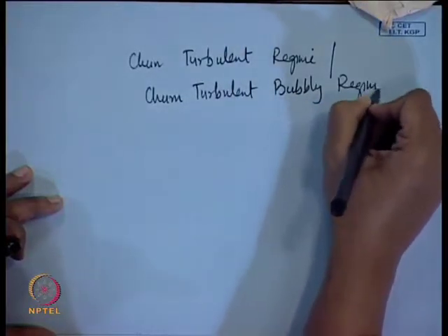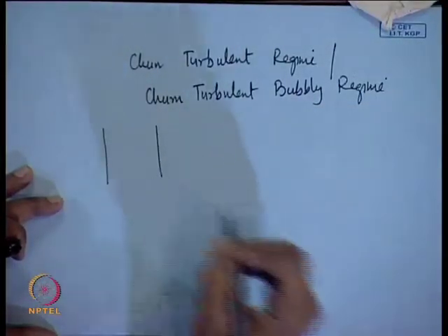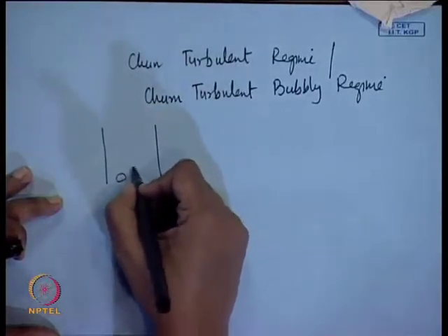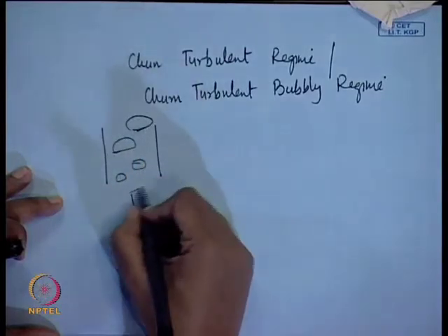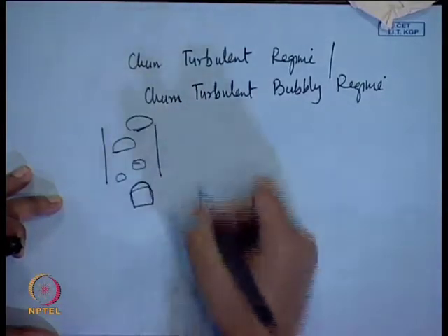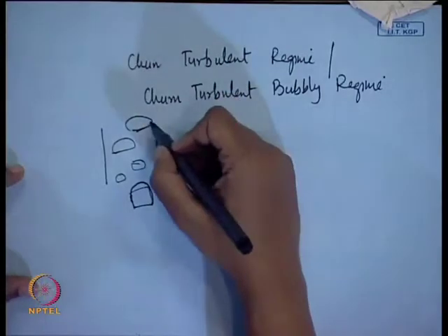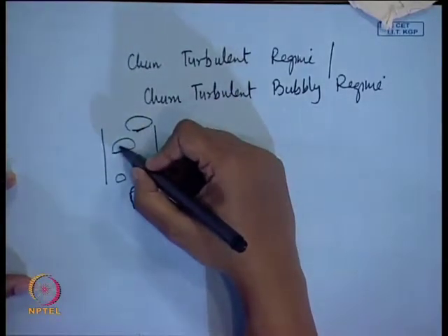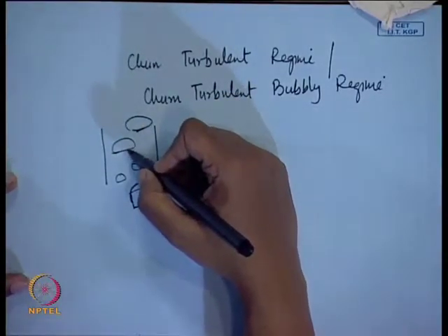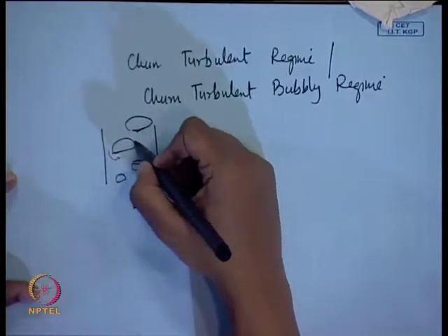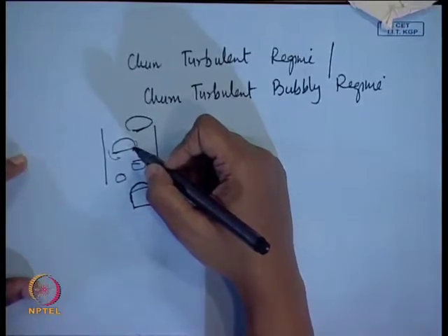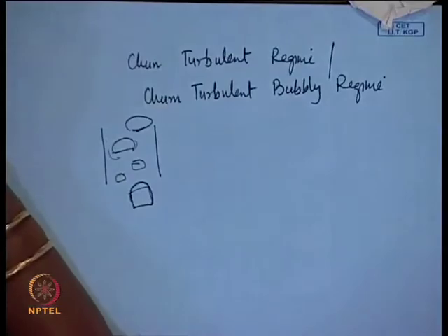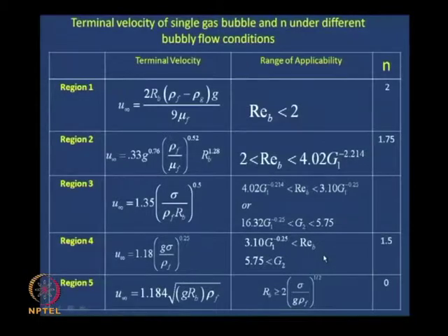In this particular situation, we find the situation which I have tried to draw in the previous slide. The situation is completely erratic and we have a large number of cap shaped bubbles. Since the bubbles are quite large, they have a good amount of wake effect and get entrapped into each other's wake, and therefore there is no influence of void fraction on J21, and that is why the value of n is 0 in this particular case.